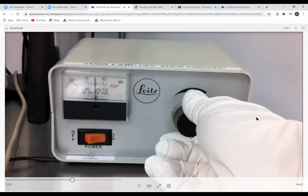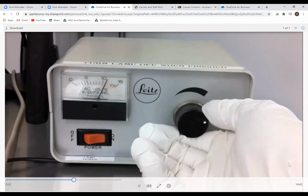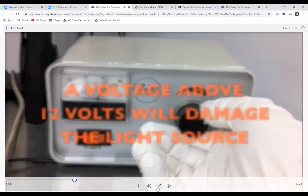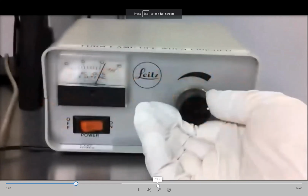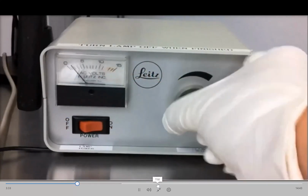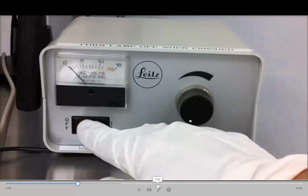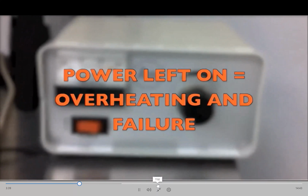May require higher voltages. That said, the intensity should never be turned up past 12 volts, as this can damage the light source. Finally, the light source should always be returned to the lowest intensity and then turned off when not in use. If the power is left on, the light housing may overheat and cause failure of internal fuses and thus no more light source.